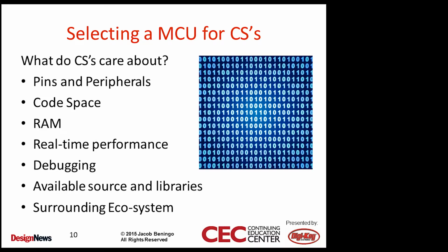Now, if we move on to slide number 10, we have the perspective of the computer scientist. The computer scientist is going to share some of those same concerns. They're going to care about how many pins are available, how many peripherals are available. But they're going to care about the pins from a slightly different perspective. A lot of times we try to get insights into the code that we're writing, and the only way we can do that is to set up different pins on the microcontroller and pulse them or maybe put LED indicators or do interesting things to try to get performance information out of the microcontroller.